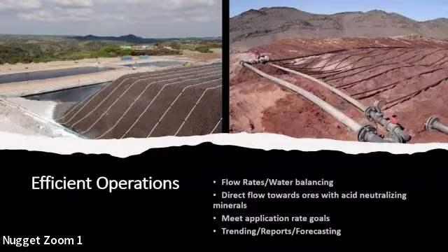In addition, we performed complementary studies, doing some down the hole tests. And we also did dissipation tests every 5 meters in all of the testing boreholes.